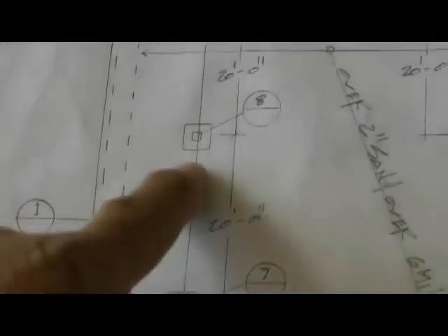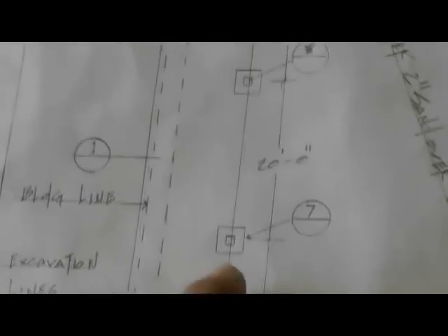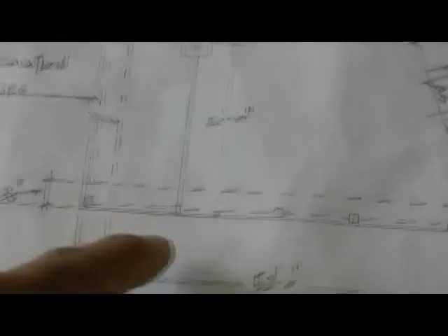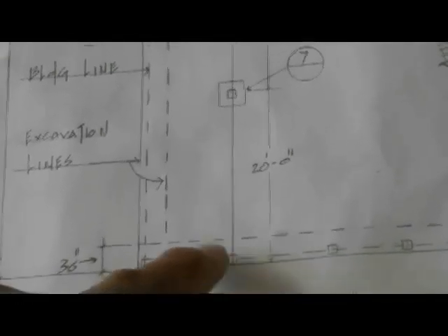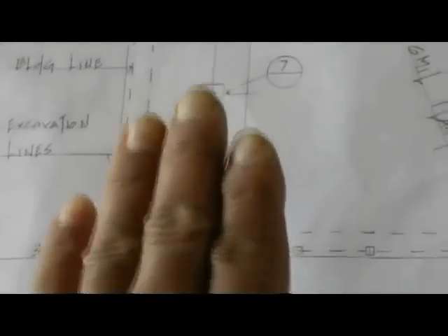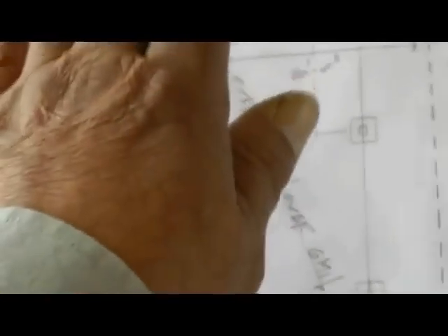With that sort of a diaphragm, it's necessary that we put these pad footings in place, because the weight they're going to be carrying is only the weight of the roof rafters and the corrugated metal, and probably a couple of guys at a time, who will systematically begin where it's comfortable for them, placing their corrugated metal from the middle of the ridge and out on top of the rafters.